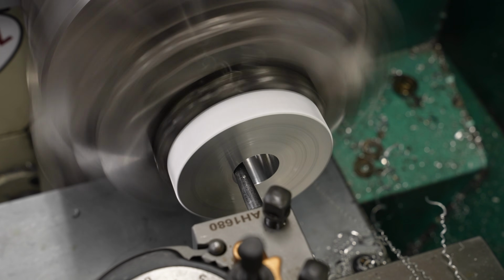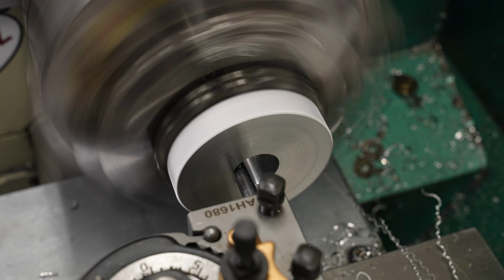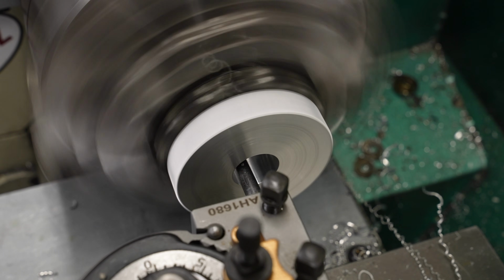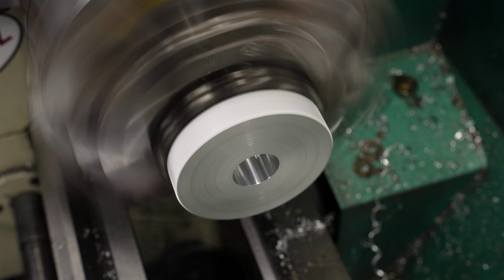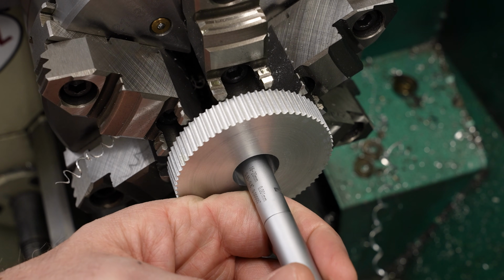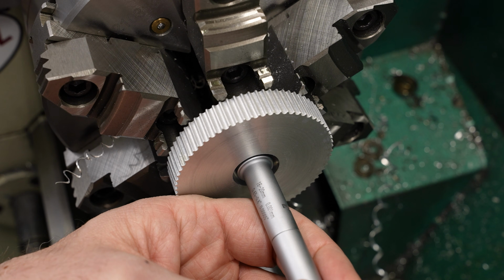And taking a fine cut in aluminum with the A9 lubricant with this tool does leave a very nice surface finish. Get all the way through, pull it off the surface before we extract it just to make sure we don't leave a spiral groove in there, and then measure with the 3-point mic to see what dimension we hit. You'll remember last time I hit 20 millimeters right on the nose. What did we hit this time?